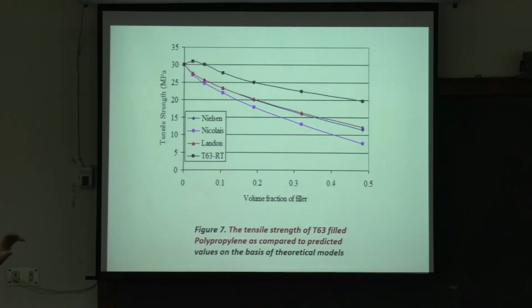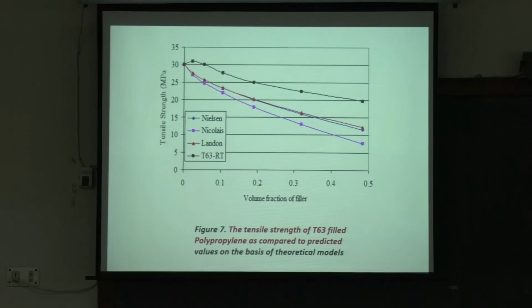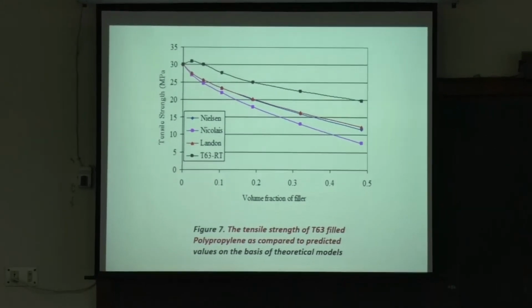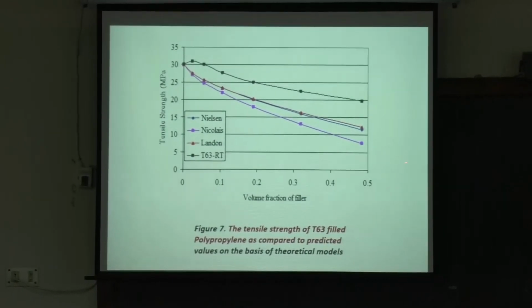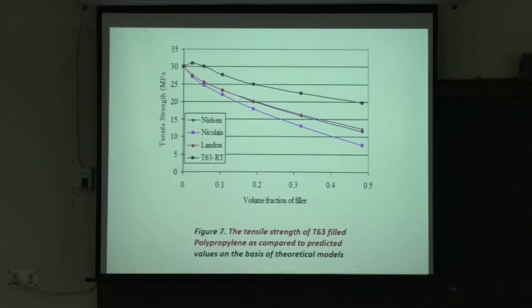So obviously all the bad things which are happening in those models, in this fly ash model using up to 80 PHR, that did not happen, and it's significantly higher even with 50 volume fraction of fly ash. All right, it still maintains. So that was a positive thing.